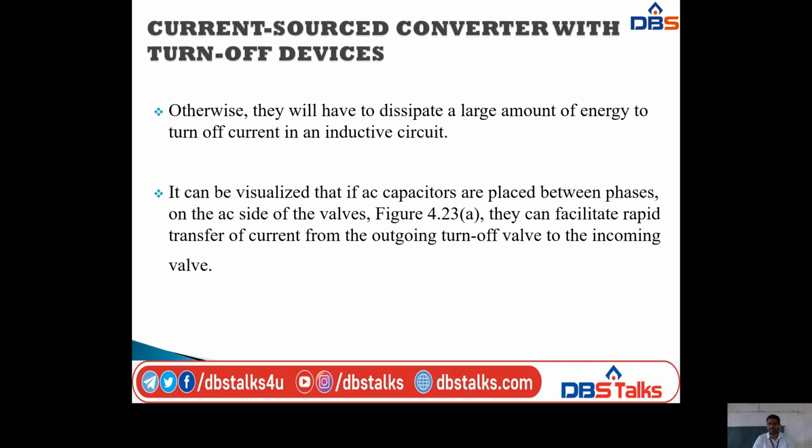It can be visualized that if AC capacitors are placed on the AC side of the valves, they can facilitate rapid transfer of current from the outgoing turn-off valve to the incoming valve. So here I am putting the AC capacitors on the AC side of the valves, that is the thyristors. Here I will show the diagram, and you will understand this.